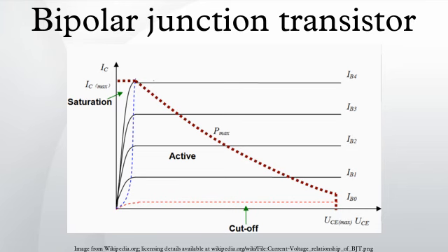Punch-through. When the base-collector voltage reaches a certain value, the base-collector depletion region boundary meets the base-emitter depletion region boundary. When in this state, the transistor effectively has no base. The device thus loses all gain when in this state.